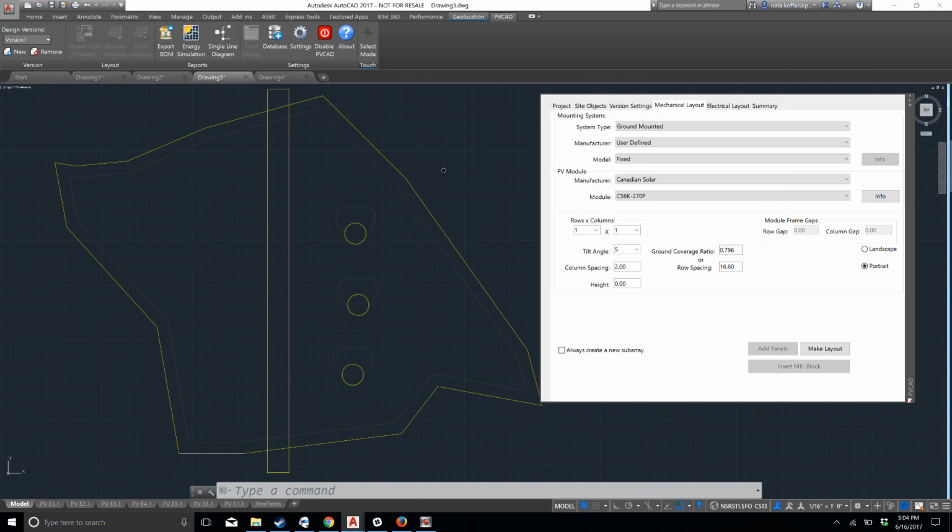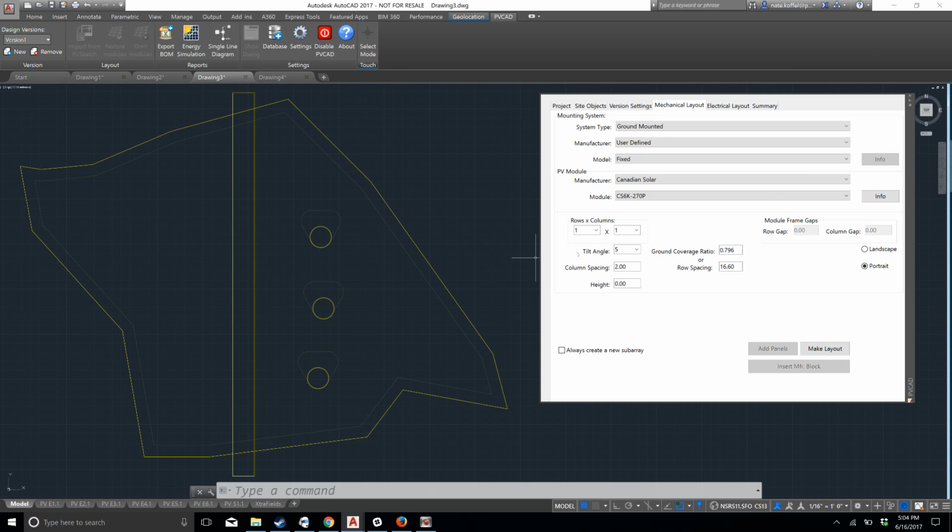after you've chosen the PV module that you want, you're going to have to make some decisions on your rows and columns. So this is the actual table that we're setting up, the table that you're going to have in front of you, whether it's going to be a fixed tilt or a tracker, whatever it is going to be. This is what you're going to use to simulate that design. So let's pretend it is 4 rows deep and it is 20 modules long.